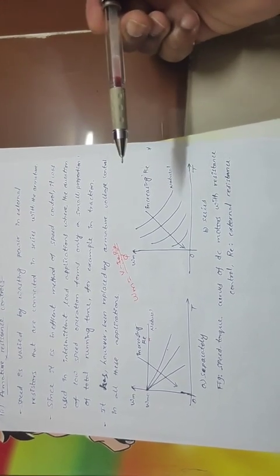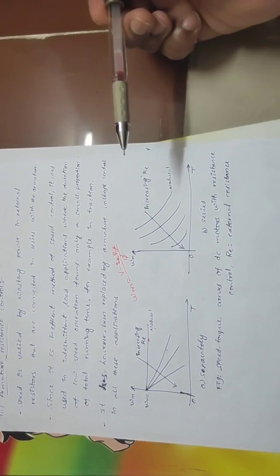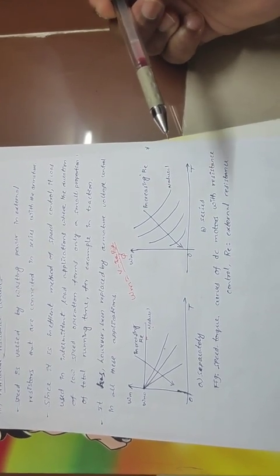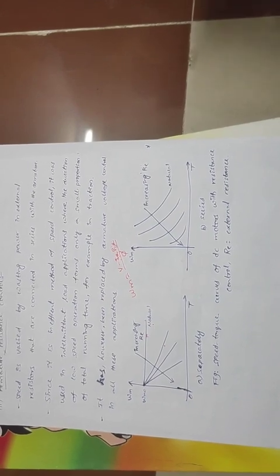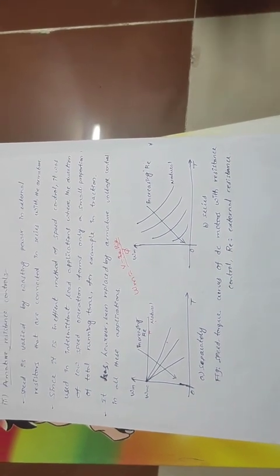However, in a few applications like intermittent load applications, where the duration of the speed control is limited, for example in traction, where we need to control the speed frequently during frequent starts and stops, we can go for the armature resistance control method.